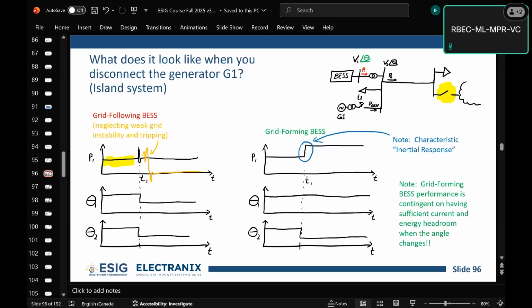But it's not an instantaneous PLL, right? The PLL still has a bit of work to do, and so it takes a moment, and in that moment, it's not perfect, and you get a little bump. So what happens here is theta 1 and theta 2 track each other. So theta 1, using that PLL, tracks theta 2 so that this distance is constant.